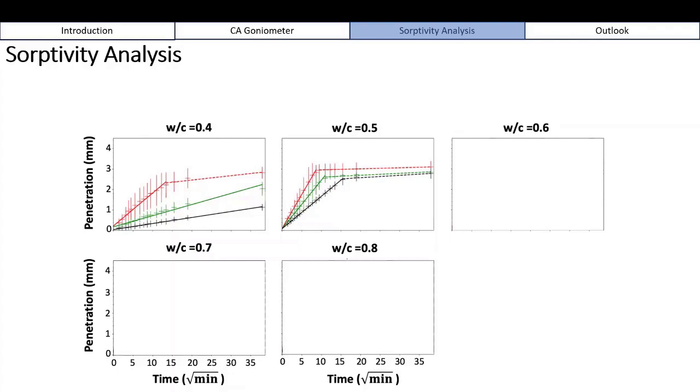But for real concrete surfaces where we have carbonation, the surface is more densified because of carbonation. So similar to carbonation depth, where we split the sample and spray phenolphthalein, we have to test it on a fresh concrete sample. Or at lab scale, we can put it under a desiccator to make sure it's not carbonated.